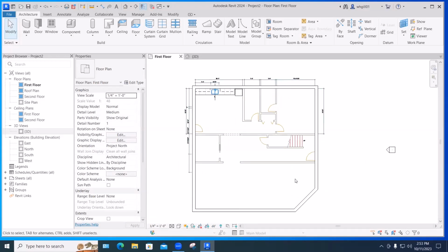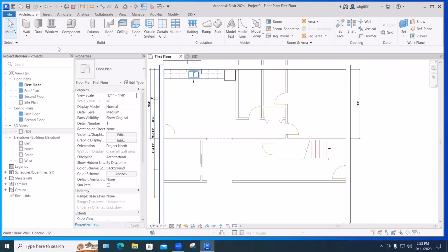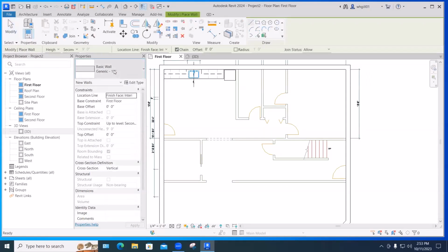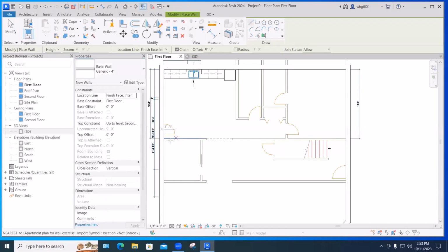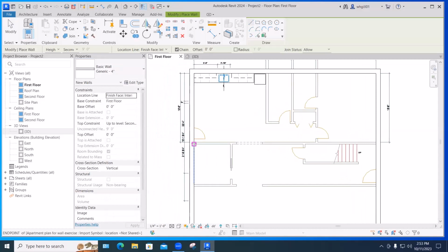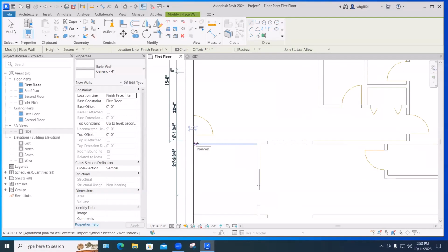And the question for these is, do I want to go down the center line of these walls? And I would say no, because we don't know where the center line really is for most of them. It doesn't matter which is the inside and which is the outside, but let's create that wall type and then see what we can do with it. Sound good. Let's use the wall tool. And again, I'll use maybe a slightly narrower wall to start with, this generic 4-inch wall, so I can see the other one sticking up past it. And inside, outside, it's the same stuff really.